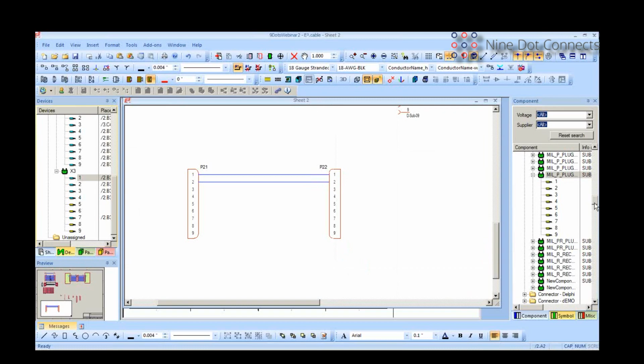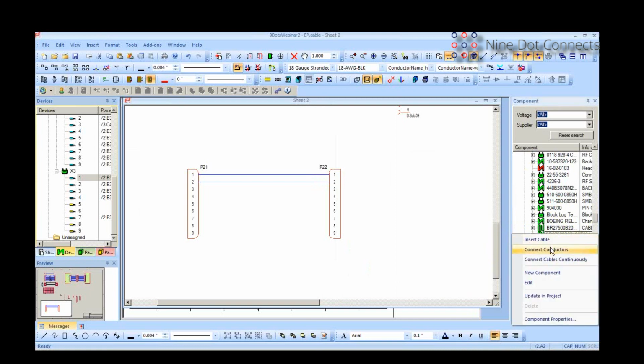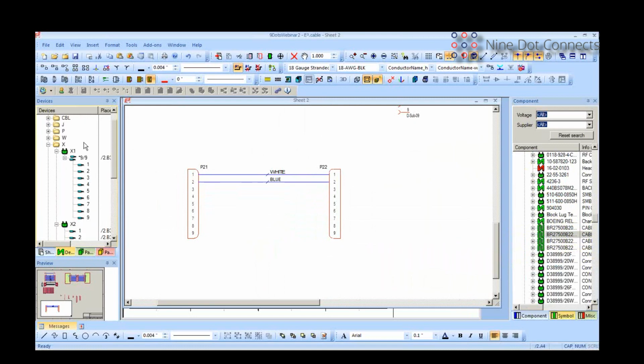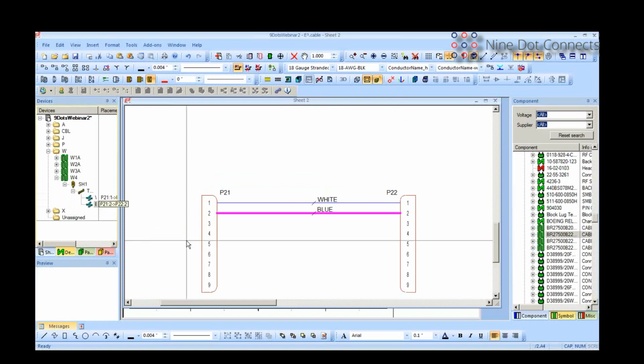And I'm going to connect these with a shielded cable. So if I look here, I want a shielded twisted pair. There's a shielded twisted pair, and I'm going to connect this. And so there's my connection made. By the way, if I close this for a second, what we can see is that's the original cable, and this is this cable. I think it's this one. So there's the shield, there's the twist, and there's the conductors of that connection.